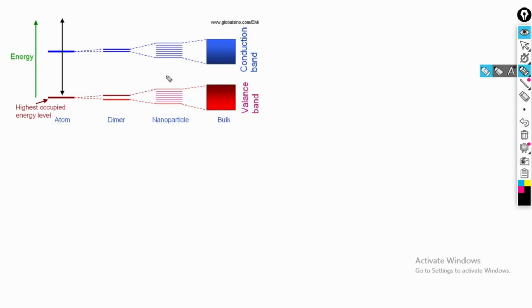So we will proceed with that same concept, but now we will use the energy band theory. Now what is the concept, what is the origination of that energy band theory, energy bands? Okay, so let's say we consider a single atom which has orbitals, the energy states or energy levels. Every atom has shells or orbits in which the free electrons are moving. Each shell has its own energy, and that is different from the energy of the other shell.